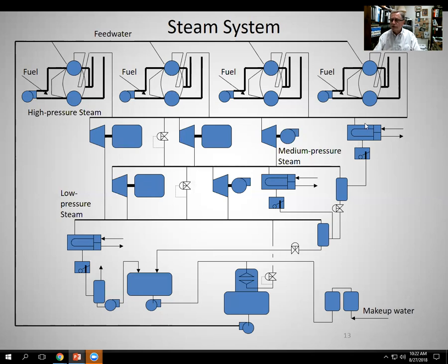Here we've got high pressure steam heating the fluid. We've got the steam trap passing into a flash tank. We get some medium pressure flash that goes into the header. The condensate, which is controlled, then flows down to this lower pressure tank, so we get some more flash out of that. And this lower pressure tank is also receiving the condensate out of this heat exchanger down into here.